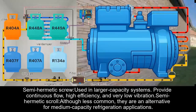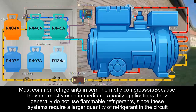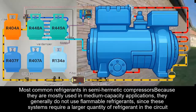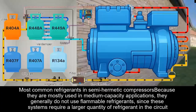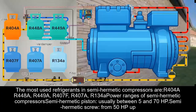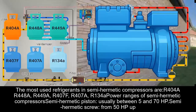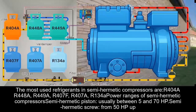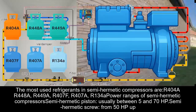Most common refrigerants in semi-hermetic compressors: because they are mostly used in medium-capacity applications, they generally do not use flammable refrigerants, since these systems require a larger quantity of refrigerant in the circuit. The most used refrigerants in semi-hermetic compressors are R404A, R448A, R449A, R407F, R407A, and R134A.